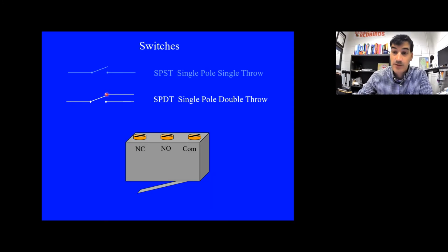All right, so we always draw it, like I said, in the de-energized or deactivated state, like you just pulled it off of the shelf. So normally, this switch is going to have a connection between the input and this pin right here, this connection. So this connection represents our normally closed connection. It's normally closed, meaning there's a connection from this terminal or pin to the input. So this right here is represented by this screw terminal right here. So you can put a wire and connect it to this screw terminal right here.